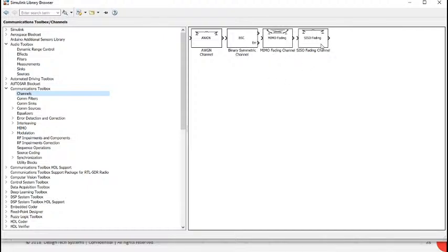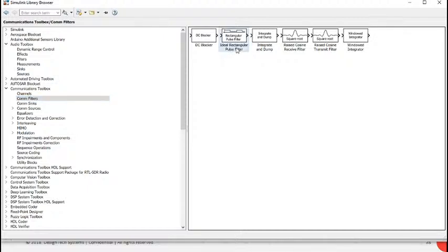MIMO, that is a massive MIMO, multi-input, multi-output antenna system. SISO is also available. AWGN is also available. Some filters are available there. So if you have any query about filters, after modulation you can use this raised cosine receive filter, right? You just have to connect all these blocks there. Okay. DC blocker is also there at the receiving end. Let's say you want to use the DC blocker, whatever DC is coming you have to block, you just have to add it one by one. That's all. Okay. There are some things available.